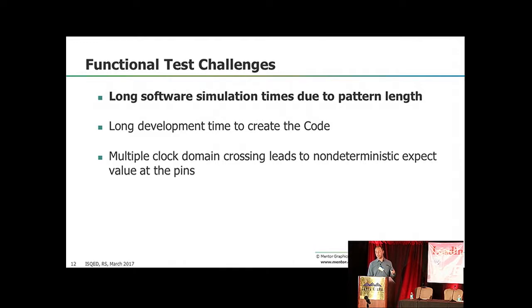Also, once you get it on the tester, now that you're running functionally, you are crossing multiple time domains and multiple voltage islands. So it is very challenging on the tester to make these things work. That goes back to, if you take a DFT, a design for test approach to your functional testing, you can constrain some of the non-determinism that you see on the tester.